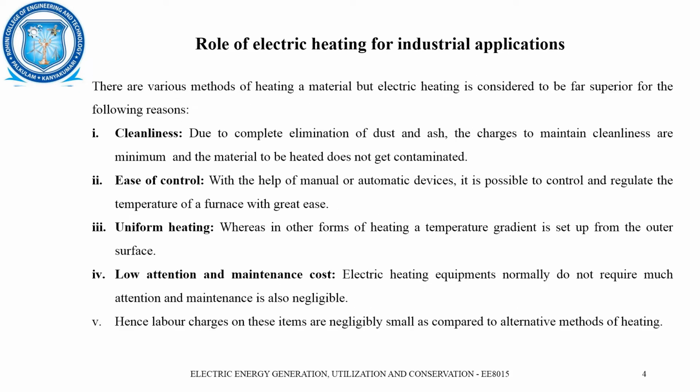Why do we prefer electric heating over the other types of heating? First is cleanliness. We do not burn anything. Second is ease of control. If we want to stop, we just have to switch off. And next is uniform heating. Since the electricity passage will be throughout the entire surface, there occurs uniform heating.